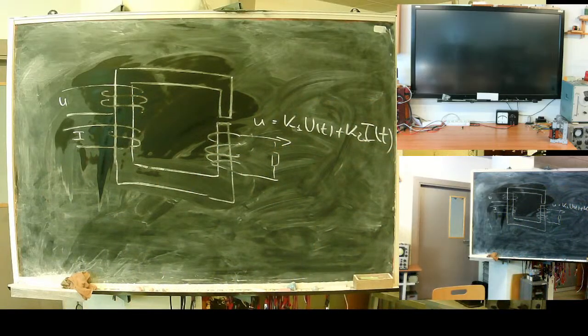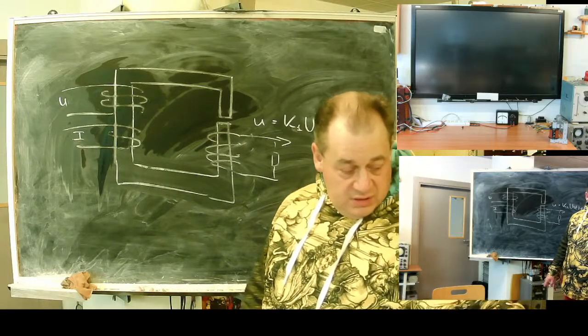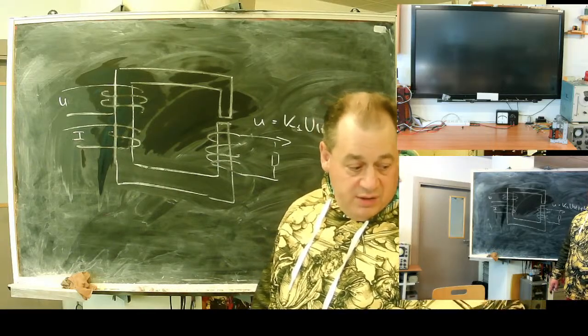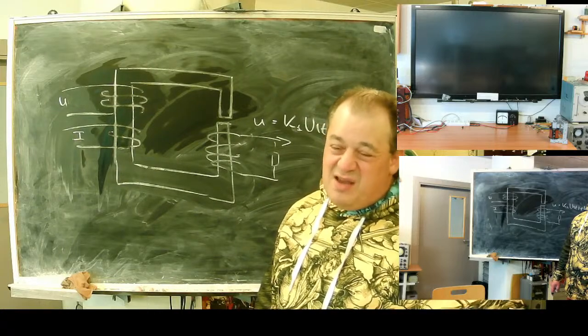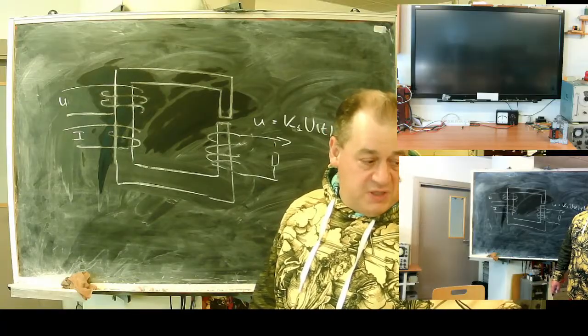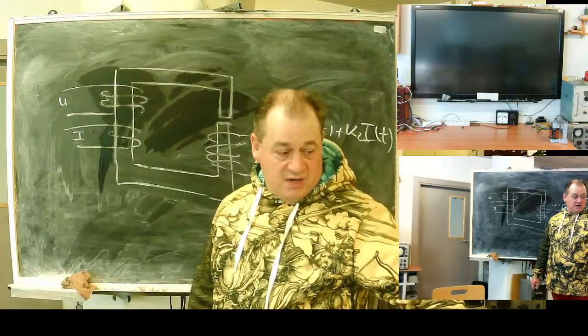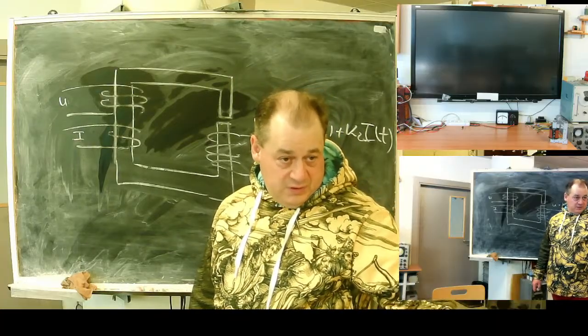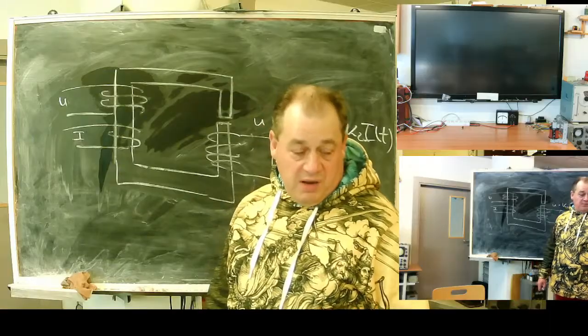And what should be pointed out? Such an input circuit puts a quite high load burden on the primary current transformer. An ordinary input circuit with a transformer consumes up to 2 volt-amps. 2 volt-amps is the cap. Usually around 1 volt-amp is the load from this circuit on the primary.